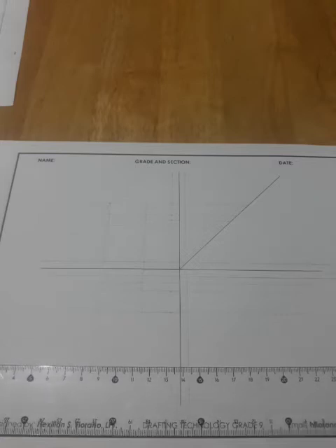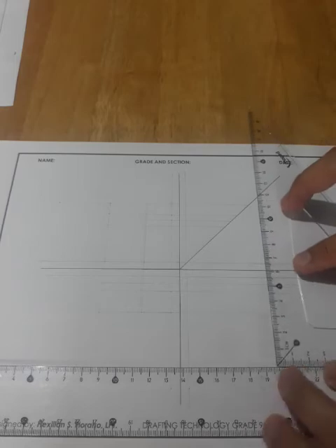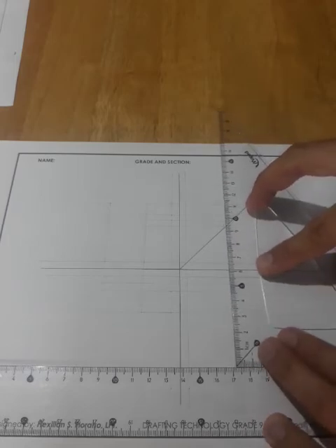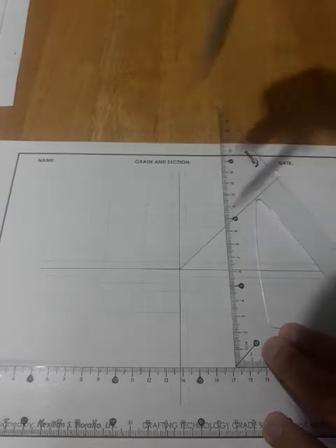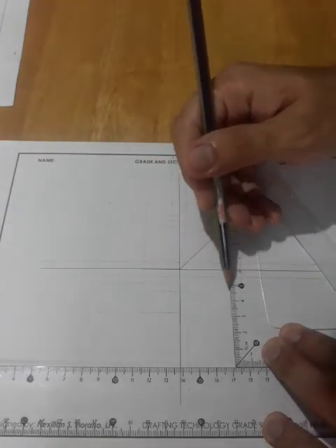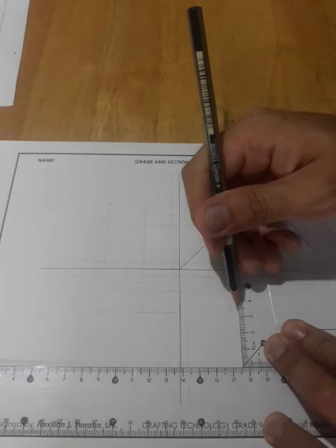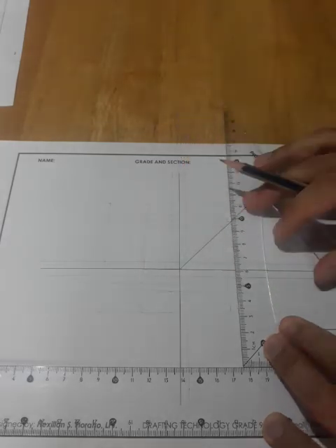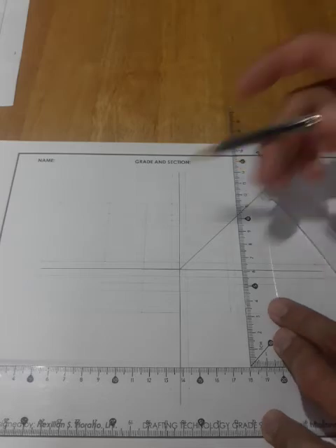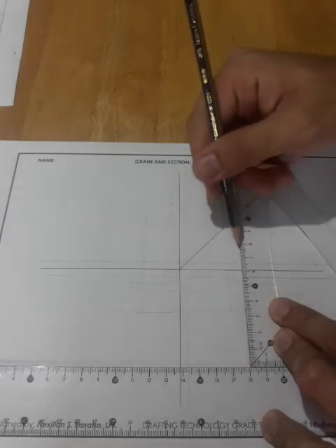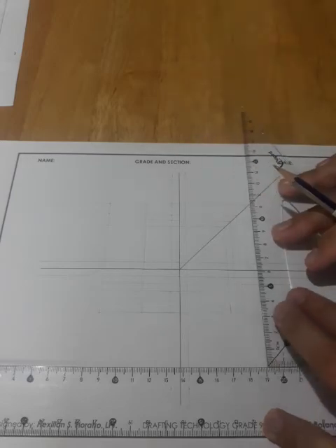As you can see, I will be using this ruler as my imaginary T-square. And make sure that if you have the border line, make sure that the ruler is parallel. So I'll be using my triangle. So let's try to project these lines up to the right side view. Okay? This is the proper way if you don't have a T-square. But if you have a T-square, you may use it. Last line.